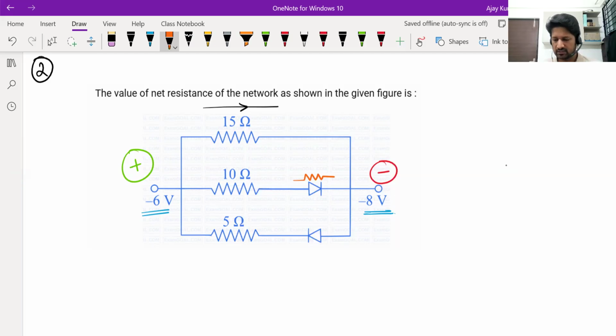And this diode does allow current from left to right. So this is forward biased. In the last branch, think of the diode as a resistor. Current tends to flow from left to right, but that would mean reverse bias current through the diode, which it will not allow. So this last diode does not allow current. There won't be current flowing in that last branch at all.